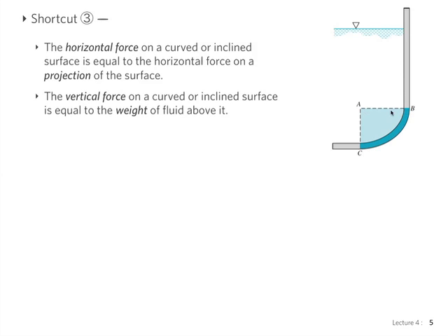To do that, we look at the equilibrium of forces for the volume of fluid contained in this curved triangle shape ABC, and we consider the volume produced by this area multiplied by a unit depth in the perpendicular direction to the sketch. That shape is going to be like this.